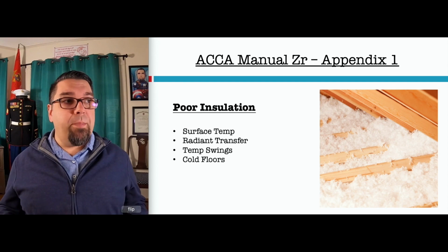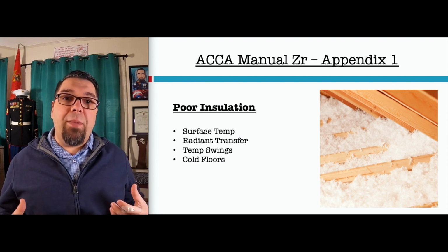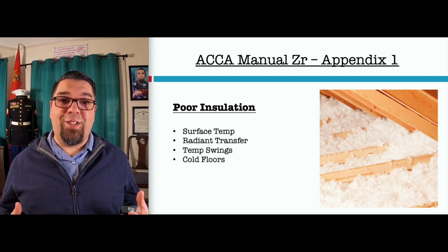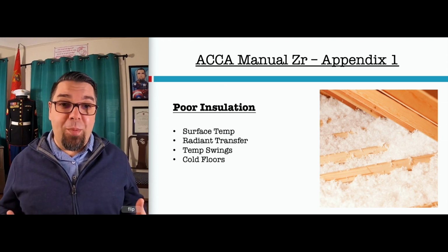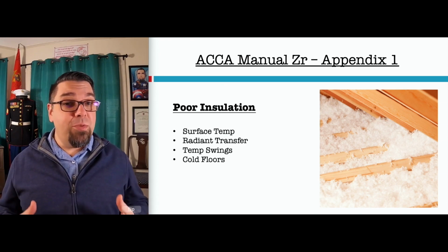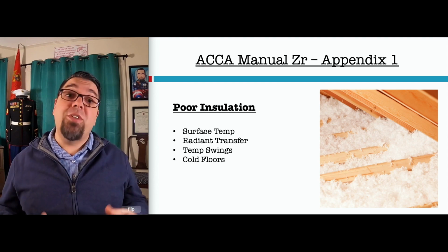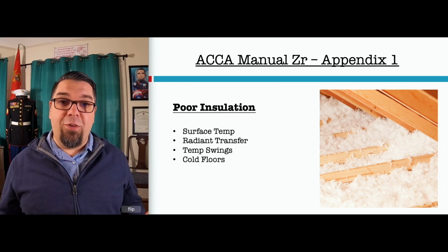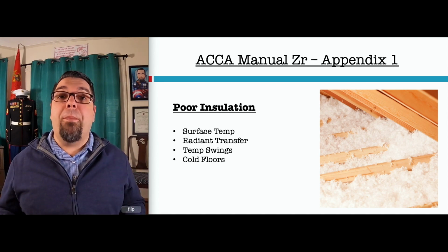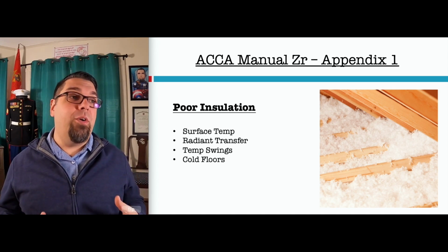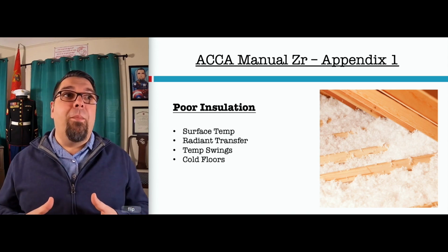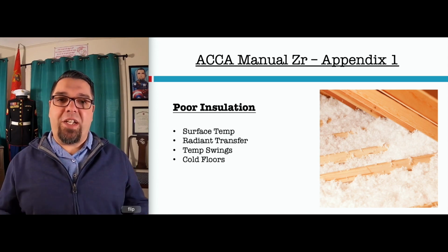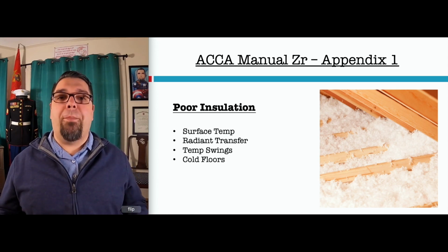And when you have big temperature swings, a lot of people start to do some crazy things with HVAC equipment. It's probably not the equipment that's causing the temperature swings. Most likely, hopefully, you sized it right and you selected the right piece of equipment. It's probably not that. It's probably the performance of the house, and you have to fix the home, not put in bigger or better or more efficient or more zones, right? We have to fix the performance of the house first in order for that person to feel comfortable in that home.